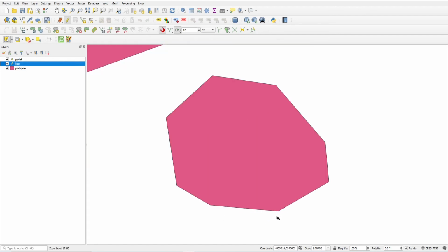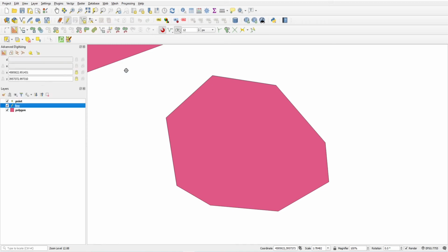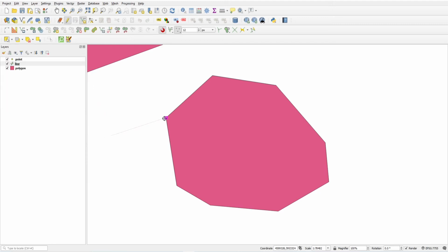Just open the polygon. I want to draw a line starting from here and snap to this, to this, and to this, and to this. These vertices. So there is a way. Draw a line. Okay. Select all layers. Snap to vertex only. This one. I'll draw a line from here. I'm just turning off this. It will snap to the vertex. I click on this vertex, click on this vertex, and click on this vertex, and this.